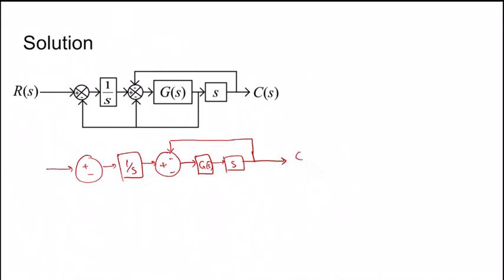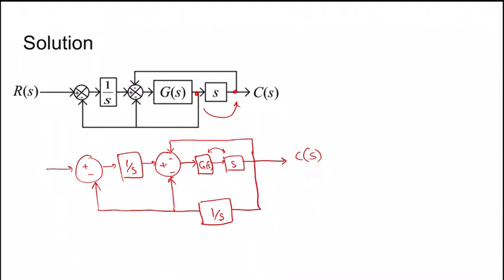And now using block diagram reduction rule 1, as we have already mentioned in the useful data, we want to take this point to here, so this point is transferred to here, and the gain becomes 1/s. Now these two, by block diagram reduction rule 2, are in cascaded fashion, so it becomes sG(s). So we can write sG(s).